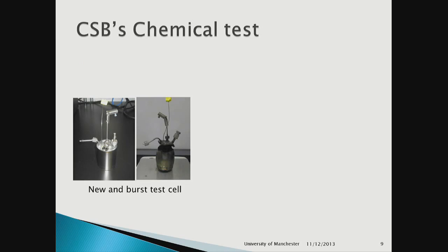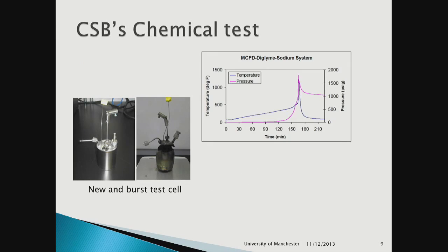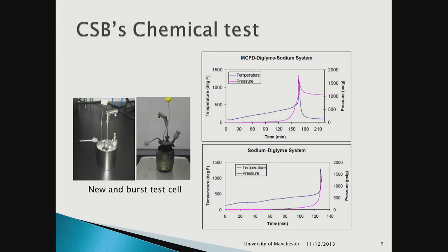And that is what it should have done. It should have just puffed it out, blown the bursting disc. So that's the reactor test system, the test system with the burst cell. It should have just blown the gasket, vented itself, and it would have been all right. That's what should have happened. It was designed to empty its contents through a 4-inch pipe.